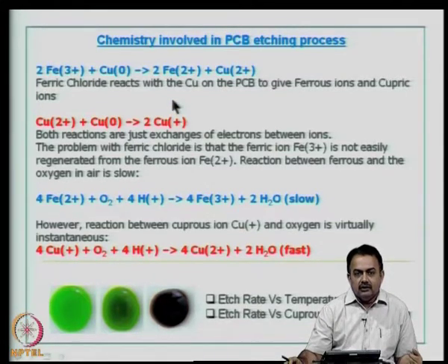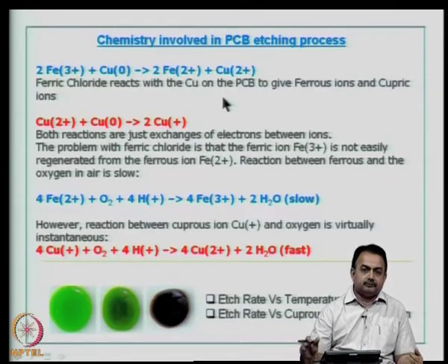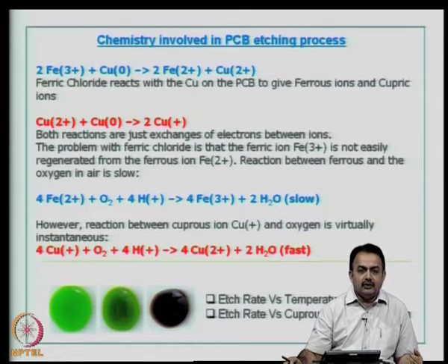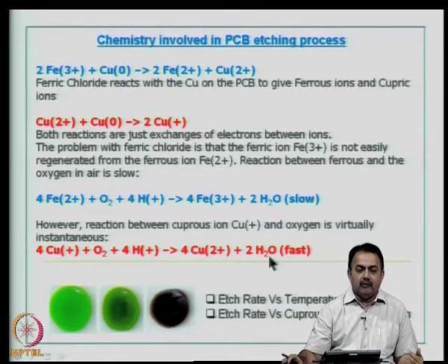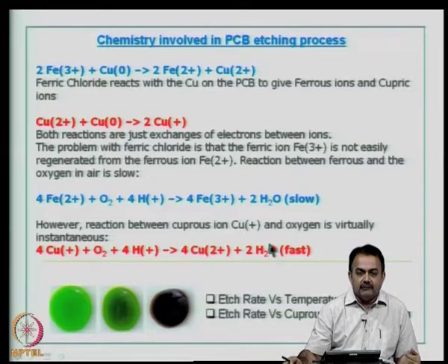And also if you look at the recycling process for ferric chloride and cupric chloride, in the spent etchant of ferric chloride you have Fe2+ and Cu2+. Therefore, the removal of Cu2+, which is a commodity that is worth removing from such a spent etchant, is going to be very complex, whereas in this case where you have only copper, it is going to be recovered fairly straightforwardly.